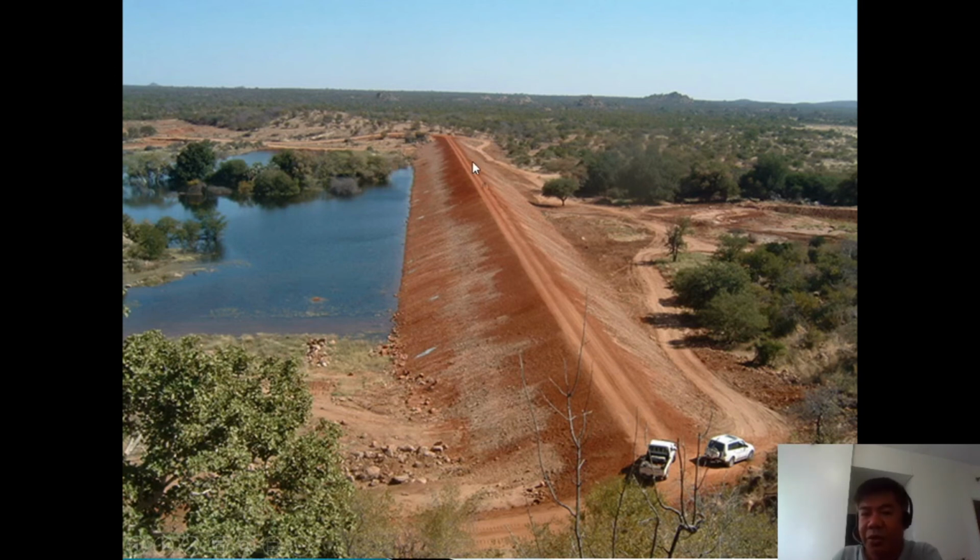Of course, you have the surcharge load, which is the load of the vehicles on this one. You have to consider the maximum water level on the upstream side to compute the hydraulic pressure on this part, and then you can analyze. Of course, the most failure-prone slope is the downstream, because the pressure here is pushing to the right, towards the downstream. So we will always consider the downstream first.